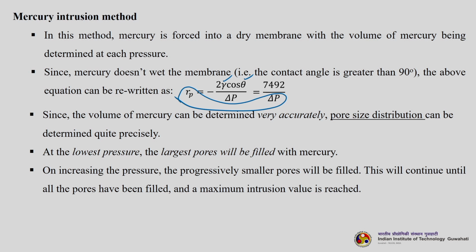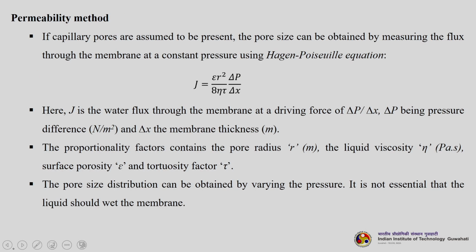So, at lowest pressure the largest pore will be initially filled. Okay. Then you increase the pressure, the smallest pore also will fill. The cost of this particular apparatus is very high. So, the next is the permeability method, which is an actual real experiment.